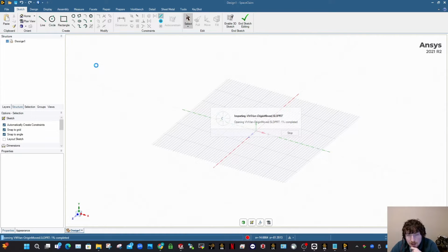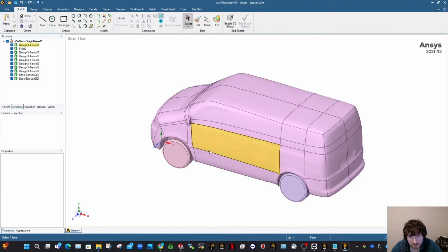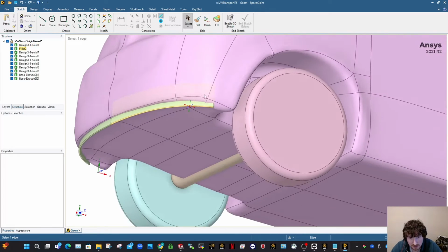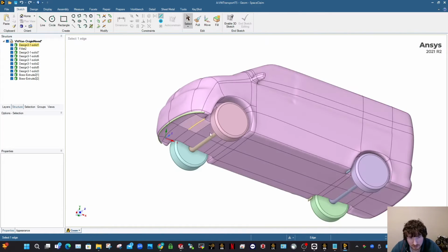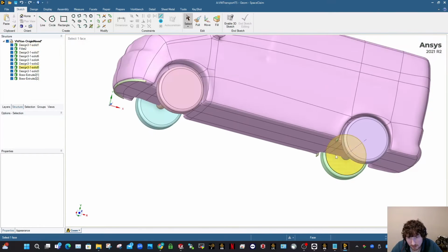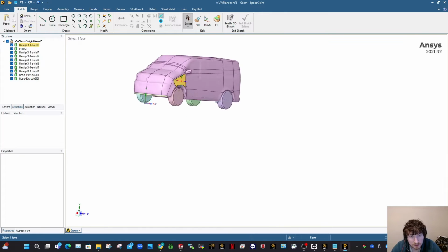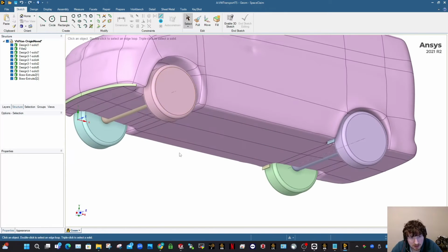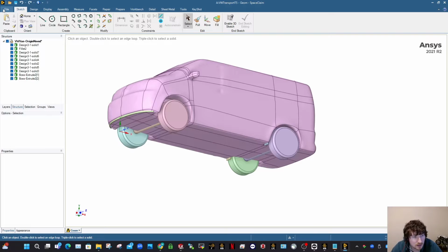And I explained that you can add other little features afterwards to it. So I'll show you here on the bottom of the vehicle, I've added a front spoiler and also a rear wheel deflector, just to improve the underside flow, and it'll also help the convergence on the RANS simulations. You see there, I drew that in SolidWorks afterwards and added it. And the same here, I drew them, and you can see I have these as separate bodies. I could just combine them all in SolidWorks if I wanted, but sometimes it can be advantageous to have them separated out like this. Okay, grand.